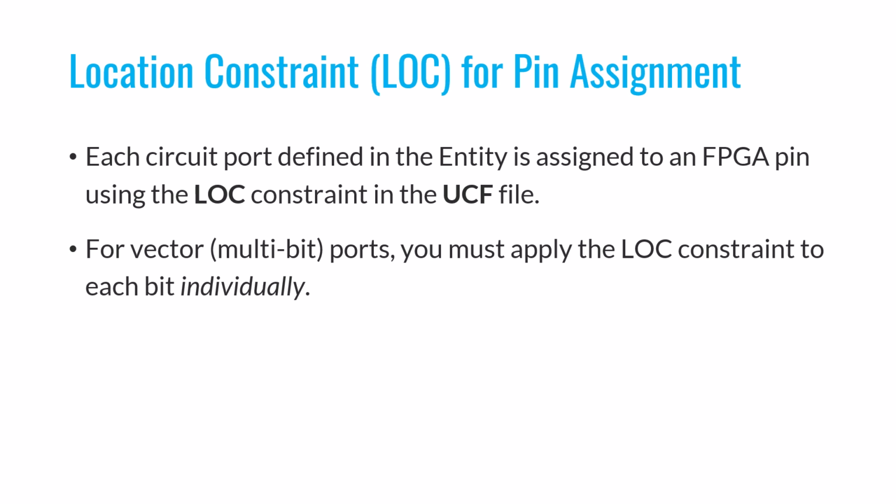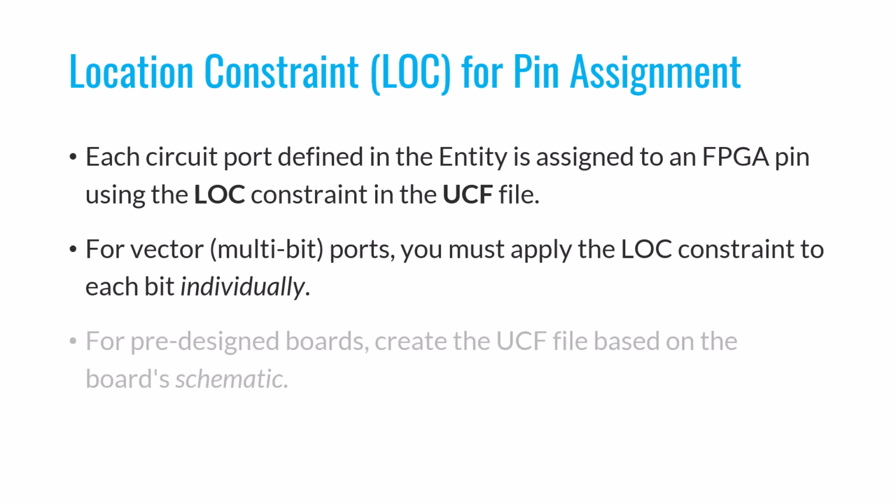Now, one thing to keep in mind is that when you're implementing a design on an FPGA, you'll usually be working with a pre-designed board. This means that it's already clear which FPGA pin is connected to which external component on the board. So, when preparing the UCF file, you should refer to the board schematic. Use it to identify which pins of the FPGA are connected to each external component and use this information to complete the UCF file. Now, to make this concept completely clear, let's go through a simple example together and see how to complete the UCF file.